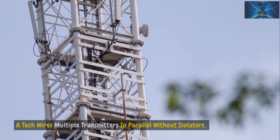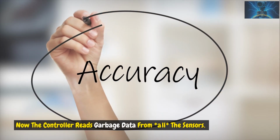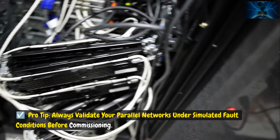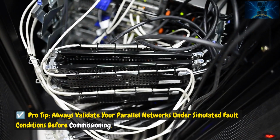Real-world trouble: a tech wires multiple transmitters in parallel without isolators. One shorts. Now the controller reads garbage data from all the sensors. Bad design, costly downtime. Pro tip: always validate your parallel networks under simulated fault conditions before commissioning.